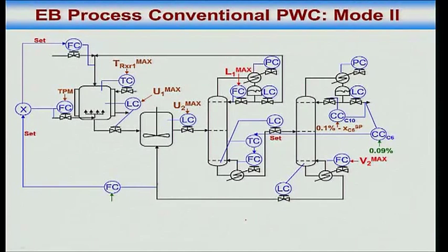But please note, when you think about it, what is actually happening is I am just transforming what is happening here to here. You see, this loop is transforming here to here. Total benzene is increasing. To increase total benzene, you will actually get the boil up to increase. Yes or no? So the problem remains.